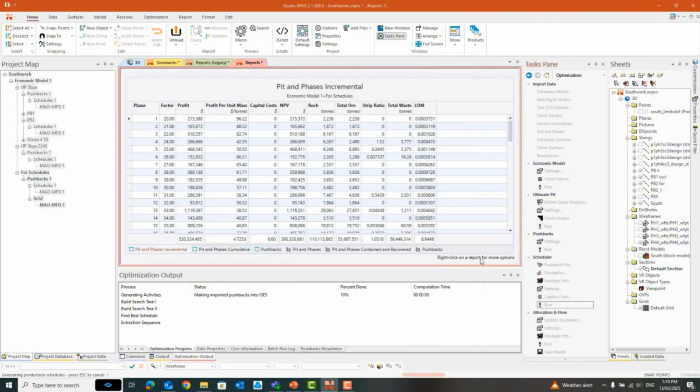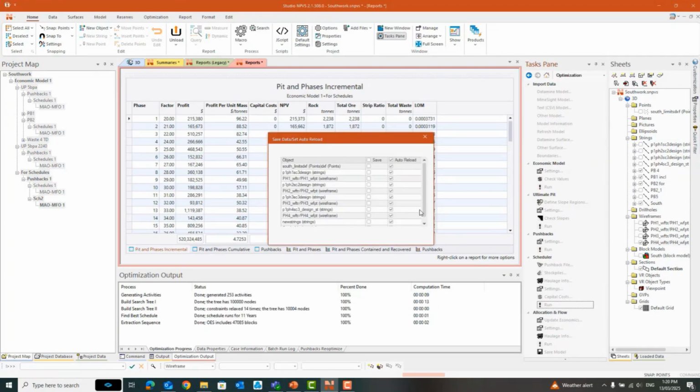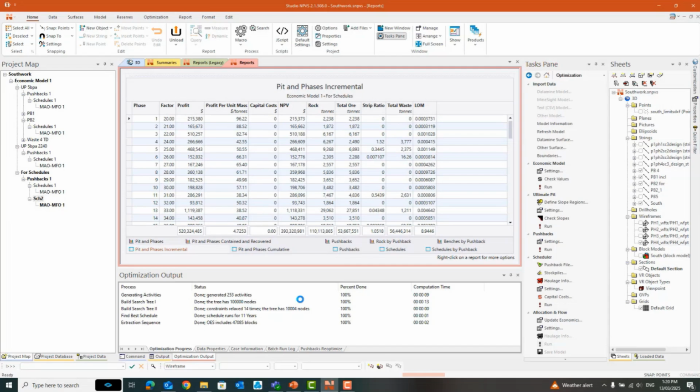So we will just run this iteration. I'm just going to take a quick section to highlight this particular parameter here. So for your optimization output, you quite often get this certain number of blocks. Make sure that you have the maximum number of blocks required coming through for your iterations. So we do in this case, so it's all good. But just keep an eye on that particular number, and if it starts to drop, maybe change your parameters because you are losing blocks from your simulations.